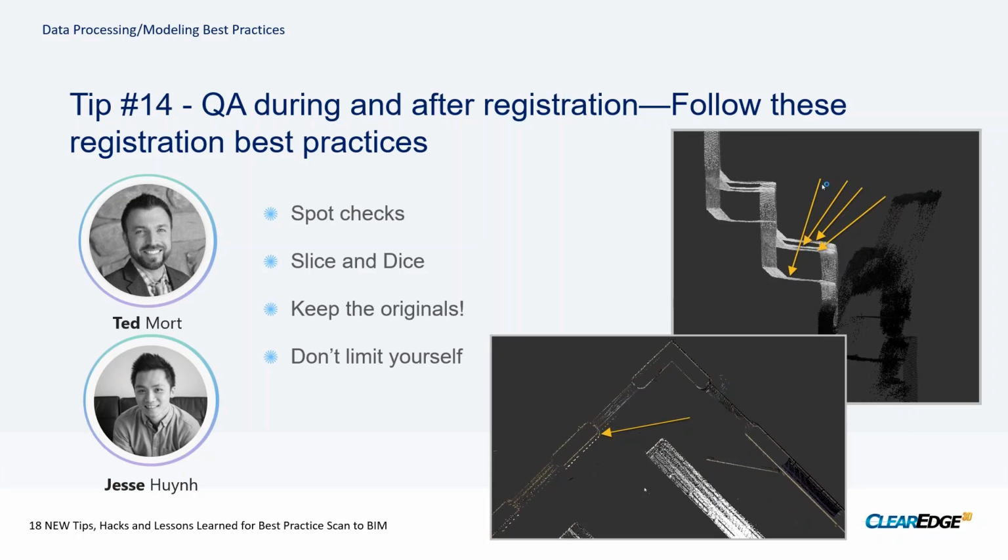You can quickly tell where scans are off because there'll be exact overlaps of outlines of walls. And you can also see that in sections when you take a look at walls. And countless times we find this early on before we even start modeling. And it definitely saves us a lot of headache that would have been caused if we didn't do that quick spot check early on.